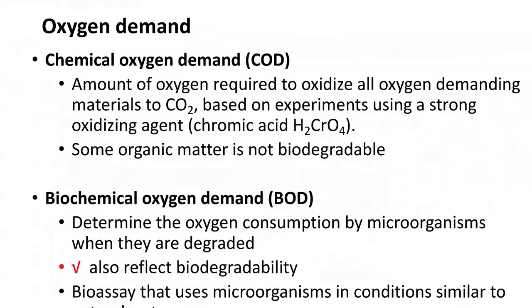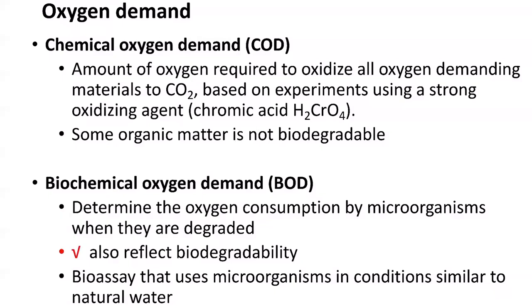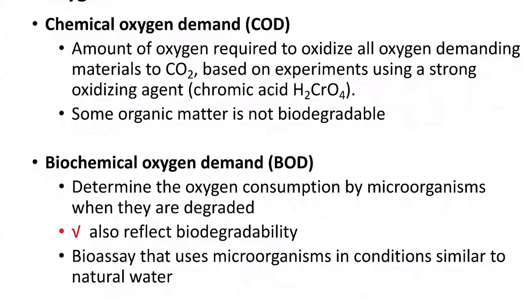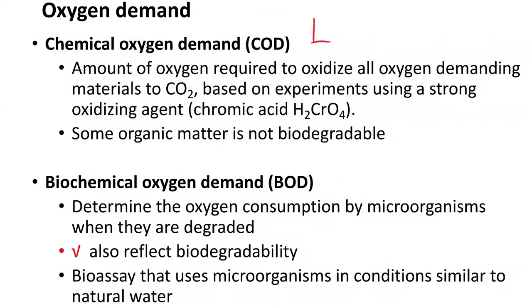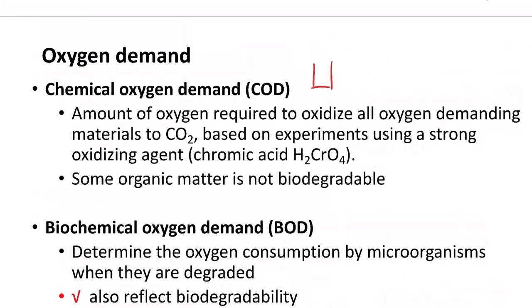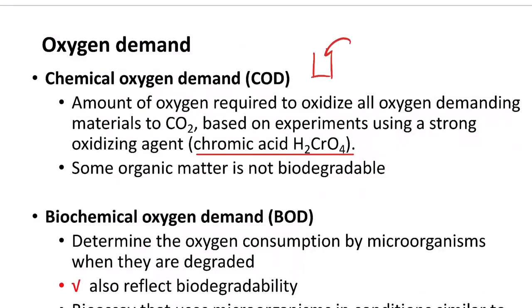So that's why people come up with other methods, for example, the chemical oxygen demand, to find a tracer or a substitute for the oxygen demand. What that means is if we collect a wastewater sample, we introduce some highly oxidizing species, for example, chromic acid. The chromic acid can oxidize anything that's either organic or living organisms.